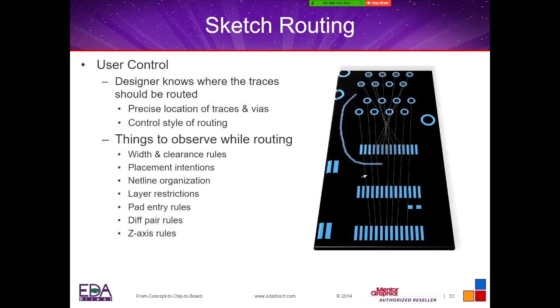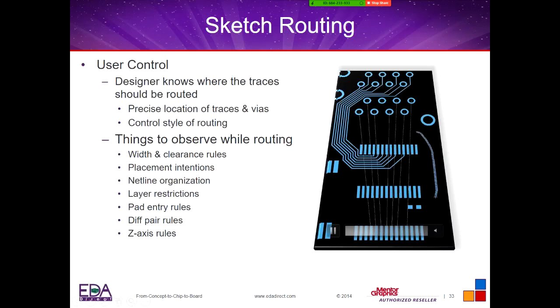Basically, it's all user controlled. You select your nets. For example, we'll select those nets and then tell them we want them to route this way, and it'll route them nice and packed. We can route them also with vias, see how the vias are. And what's nice is we can change our via patterns as well.